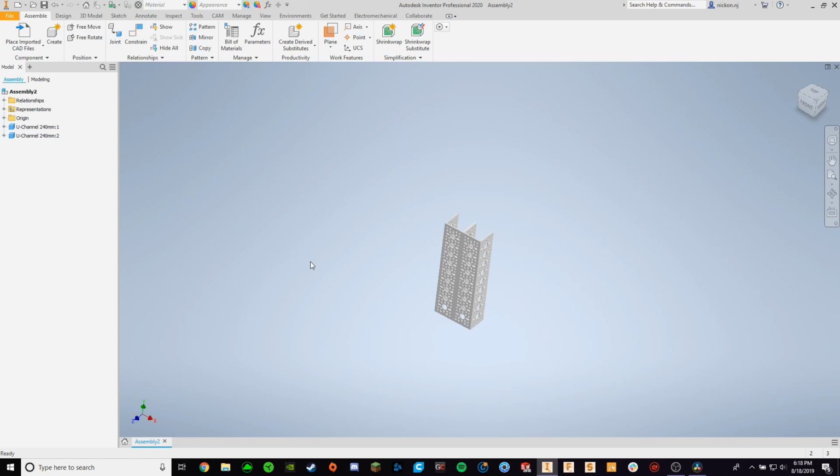Definitely, you want to ground a central part of your robot chassis. So, like your drive frame, for example, a part that you know isn't going to move that you want to sort of build off of. That's a pretty good part to ground. So, often a channel that is on your drive train, or maybe your structural frame. Those are good stuff to ground for sure.